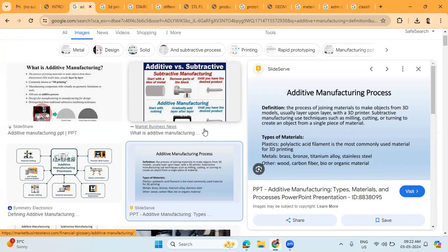Additive manufacturing works by depositing layer upon layer of material, which is fused together to form the final object. The process is highly precise and can create objects with complex geometries and intricate details. Finally, the post-processing step involves removing the support structures and performing any finishing operations on the final object. This may include sanding, polishing, or painting.